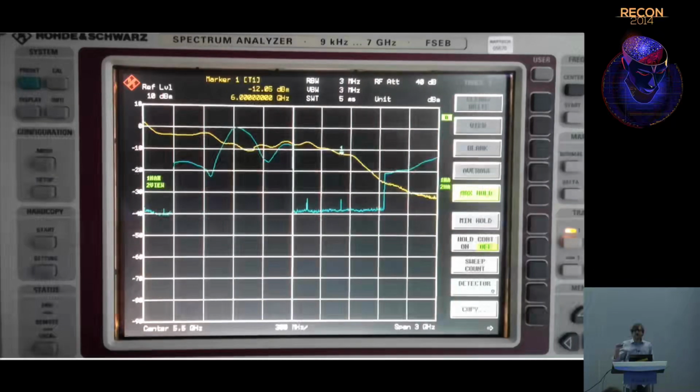However, let's talk about this little blue line. The blue trace is the result of a different operation. Here, all I did was tune the HackRF between 2.15 and 2.75 gigahertz. That's the range that the intermediate frequency transceiver operates in. I completely bypassed the front-end mixer and just ran that intermediate frequency right out to the antenna. Now, I should be seeing a significant output around 2.5 gigahertz, but that's off the left-hand side of this plot. That output would be up above 10 dBm.